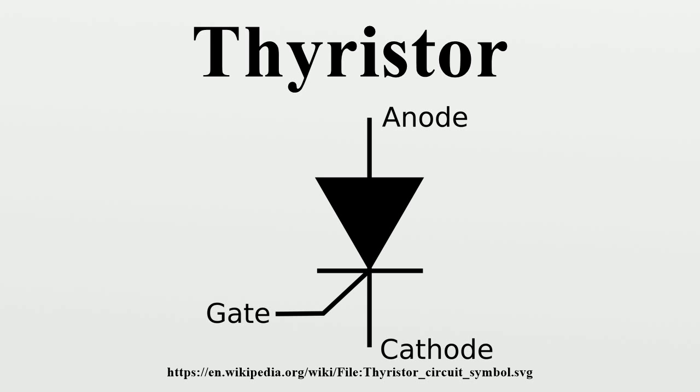MCT, MOSFET-controlled thyristor. It contains two additional FET structures for on-off control. CSMT or MCS, MOS composite static induction thyristor. PUT or PUJT, programmable unijunction transistor, a thyristor with gate on N-type layer near to the anode used as a functional replacement for unijunction transistor. RCT, reverse conducting thyristor. SCS, silicon-controlled switch or thyristor tetrode, a thyristor with both cathode and anode gates.